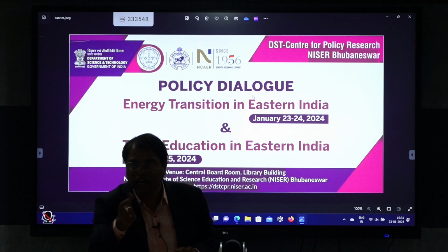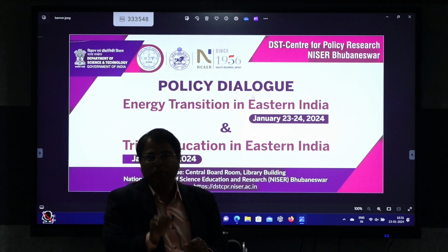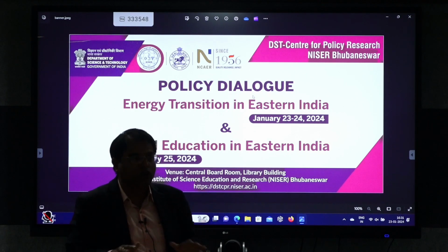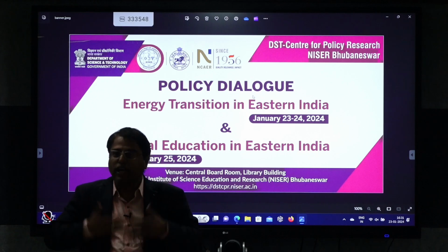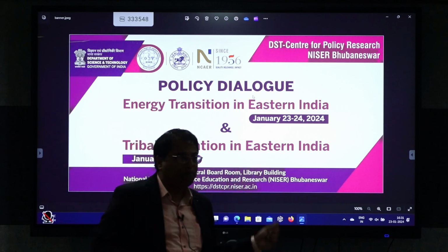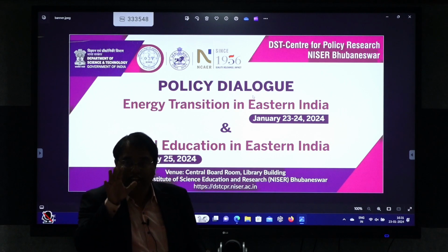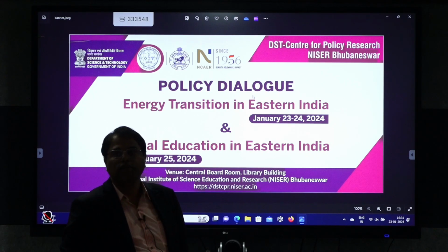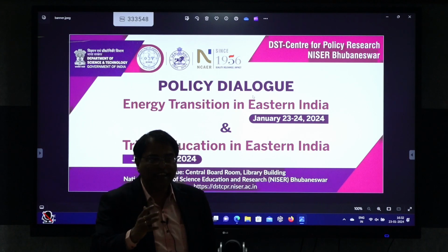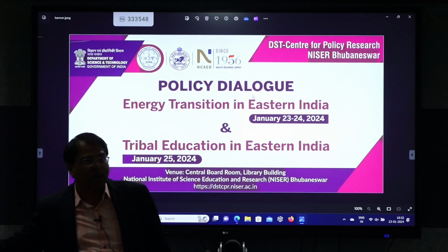There are difficulties. Now fine, we are okay with the energy transition. But let us understand: when I am procuring RE power, I am self-sufficient. Now I am an importer and I am an exporter. Because of my captive status, I am meeting my own consumption and I am exporting. But at the same time you are telling me to buy 43% of RE power from the grid. The state grid, if you go through the Grid Code Regulation 2015, does not allow simultaneous export and import of power. That means I will not be allowed to import. That means I have to stop my thermal power plant.